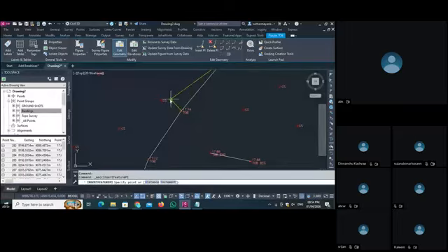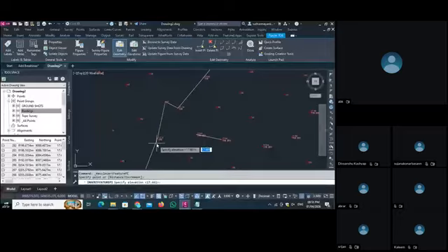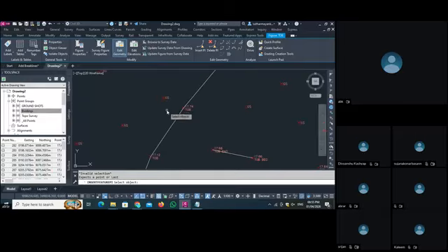and it says specify point. We specify this point. See, now the line goes through these points also. And if the surveyor gives you this line work and you understand that this is a wrong point and you want to edit it, you go here to delete PI, and see, automatically the point goes back. And if your point is not going back, you just click on the object, and you are done. Okay, so this is the edit geometry.